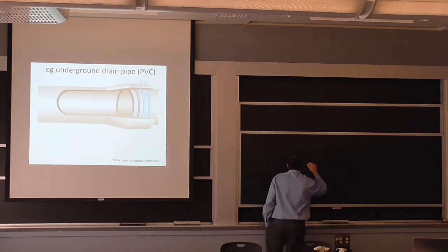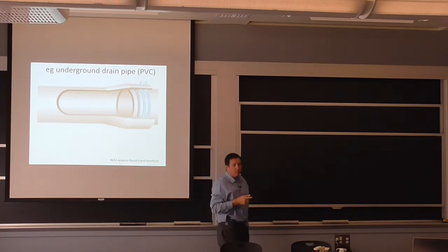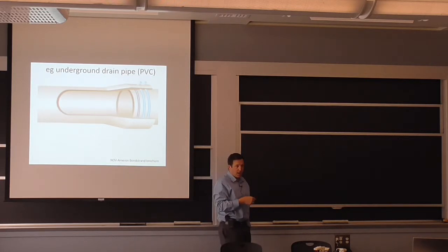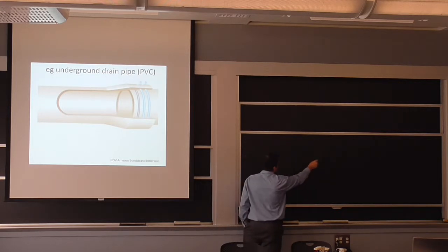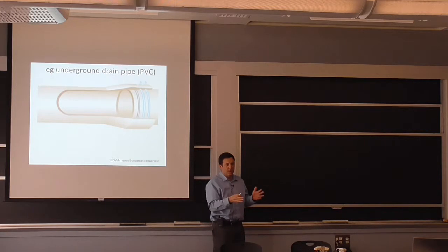So in buildings, a lot of times you don't have these expansion systems by default. You can put them in. If you expect, say, you reduce the temperature, you run out of power, or something happens in the building, or you're in construction, and you don't have everything at a constant temperature, the length of that big pipe can vary by, say, 4 inches, or something of that order of magnitude if it's a plastic.